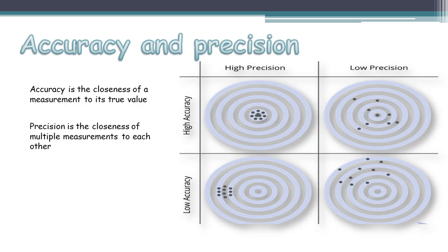To choose the correct tolerance type, we must know the difference between accuracy and precision. If a part needs accuracy, tighten the positional tolerance. If a part needs precision, tighten the feature controls like flatness, circularity, etc. Knowing the difference helps designers decide which GD&T control is required. It also helps quality inspectors have good control over the part and decide whether the process is consistent or not. So let's see the difference.